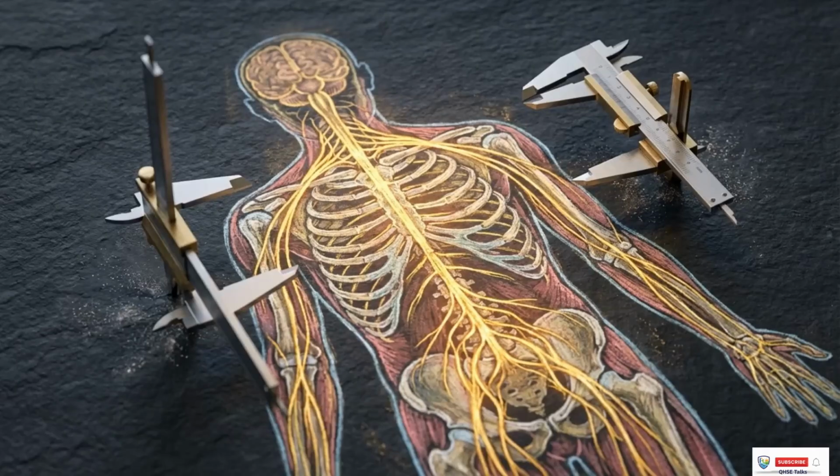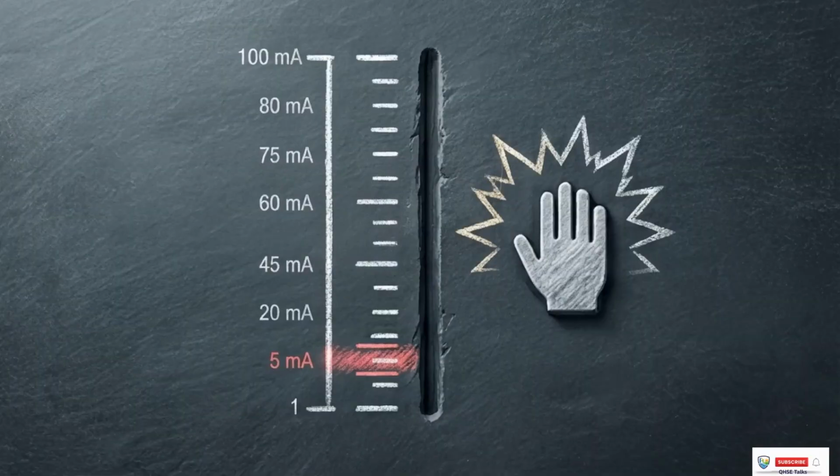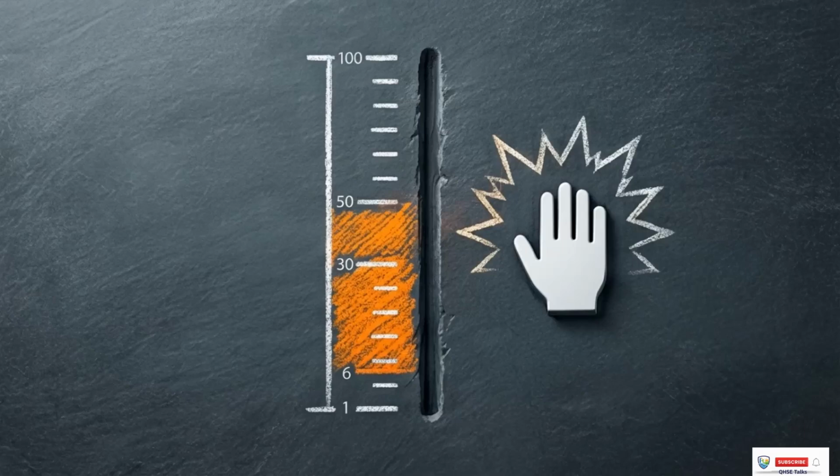The primary vector for electrical trauma is biological disruption. This disruption is driven by specific milliampere thresholds, with 1 milliampere being 1,000th of an ampere. This gauge measures the milliampere spectrum against human biology. The absolute baseline of human perception occurs at exactly 1 milliampere. At 5 milliamperes, the worker experiences a slight shock and the beginning of involuntary muscle movement. The let-go threshold occurs between 6 and 30 milliamperes. Here, involuntary muscle contraction locks the worker's hands, physically trapping them on the energized conductor and preventing release.